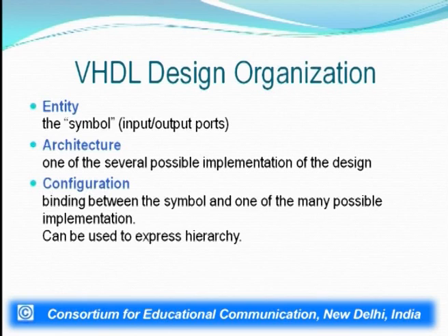For example, if I am talking about a half adder, without bothering what is inside, what gates comprise this half adder, I just assume it to be a black box and I simply define input and output ports, wherein input ports will be the numbers to be added, say A and B, and output ports are the outputs expected out of this black box once it has worked as a half adder, which will be sum and carry.